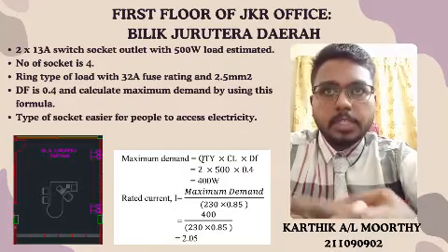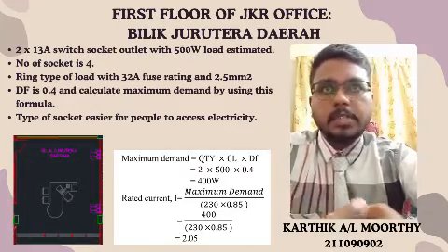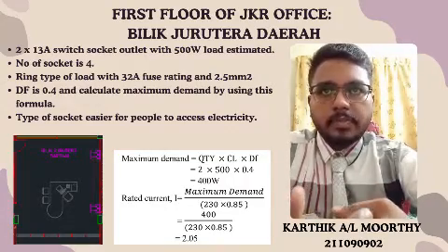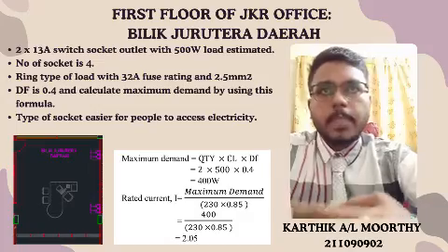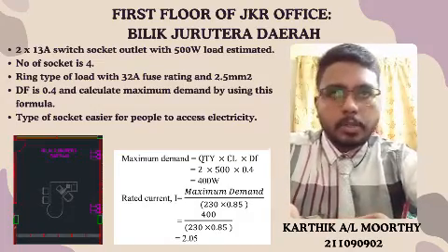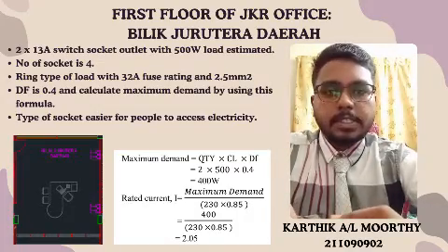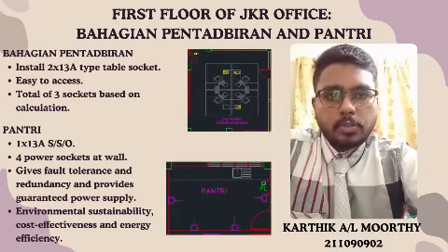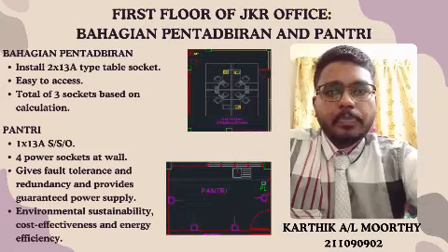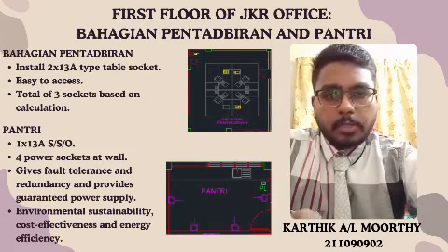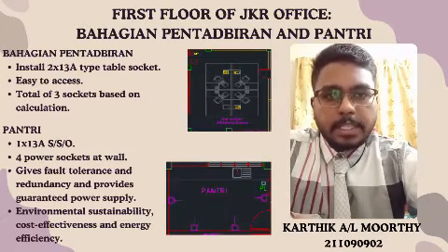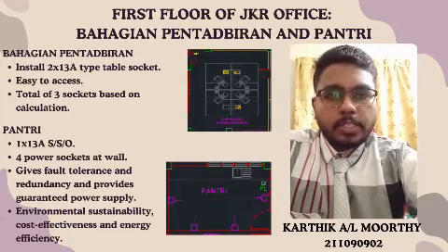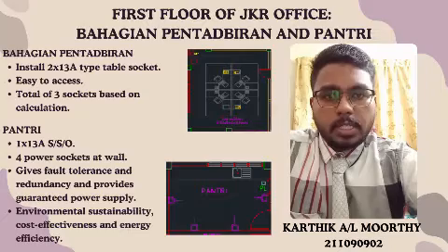This type of socket is easier for people to access electricity for a variety of uses to carry out communication, administrative work and community events. We also install this power socket according to safety laws and JKR standards. Our next example is Bahagian Pentadbiran. We choose to install 2 times 13 ampere table type socket for this particular area because it's easy to install under the table. So we install a total of 3 based on our calculation.